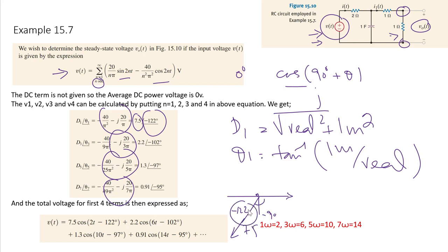So for calculating the power, we draw a shadow, the vertical projection of this thing on the x-axis. So this projection is the cos theta projection of it, and this is actually cos of omega t plus theta, because it is not only an arrow in this direction, it is a phasor.